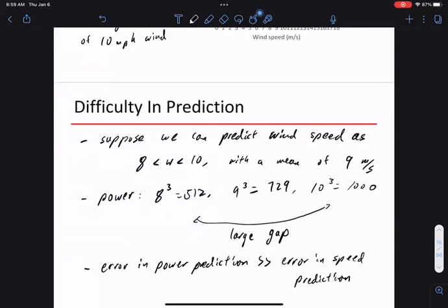This is why if you work in this industry, they'll always tell you wind speed is not wind power. Wind power is a much more complicated thing than speed. And even today, we're not very good at predicting wind power. There's just inherent error here. So this drills down to the cubic relationship: whenever you look at speed, think to power, think that's something cubed.